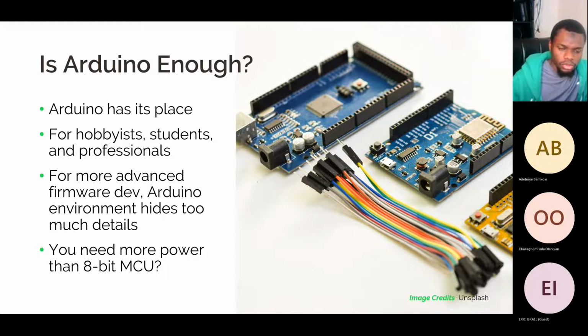But if you want to go to more advanced levels, like more advanced firmware development or some really complicated industrial design, the Arduino platform hides so many details from you that it's almost handed to you on a plate, and you don't really get into the tiny bits of detail. So you may not be able to do so much complicated stuff with the Arduino platform. That's where you need to start looking at other more sophisticated things like STM32 and ARM-based microcontrollers.